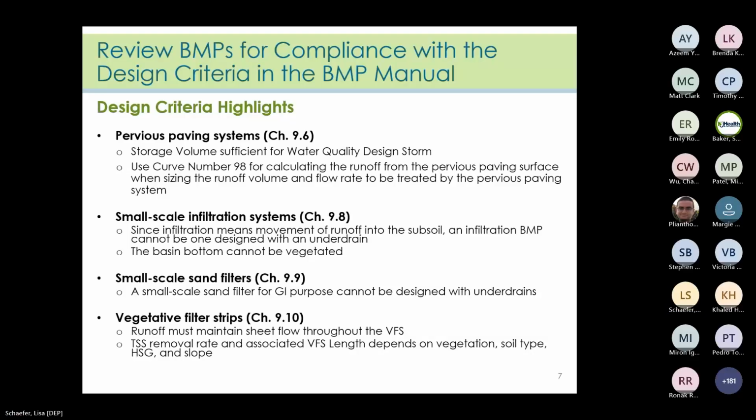Now, vegetative filter strips are not part of the BMPs that can be used to infiltrate runoff to meet the volumetric reduction standard, but they may be used to address the runoff hydrograph duration requirements, and they're found at N.J.A.C. 7:8 in subchapter 5.6(d)1.i.